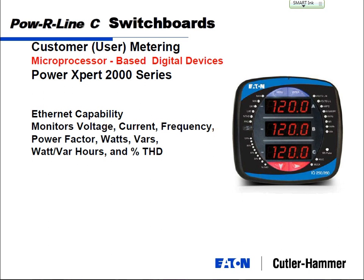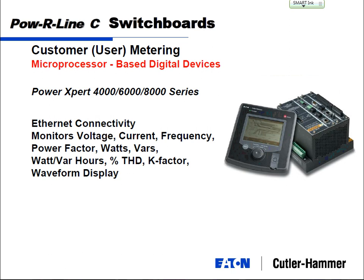And they're pretty good right now, and you can have graphs, and you can have waveforms, and you can have trends from today to 6 months ago to a year ago to look at your energy usage and how things are tracked. Now, a lot of times, you can get simple facts like power factor, bars, percent harmonic distortion, a lot of that stuff comes with it nowadays. Pretty standard as far as an energy meter. So the two basic ones are energy meters. You can get an energy meter non-communicating, an energy meter communicating, or the upper level, which I'll call a power quality meter.